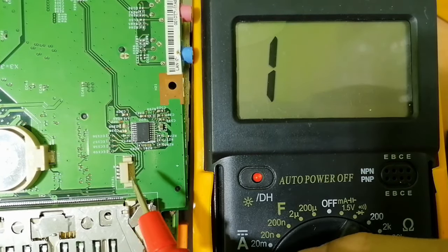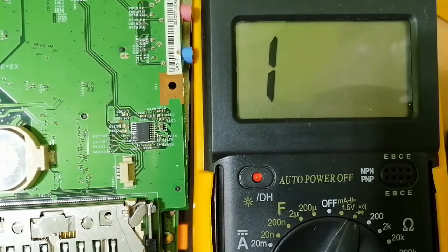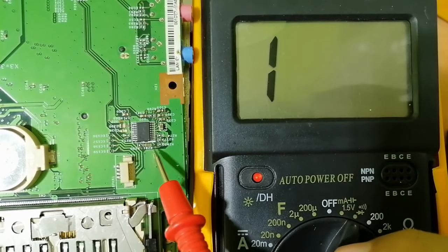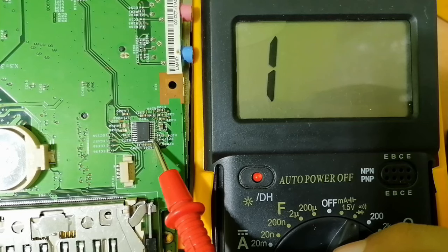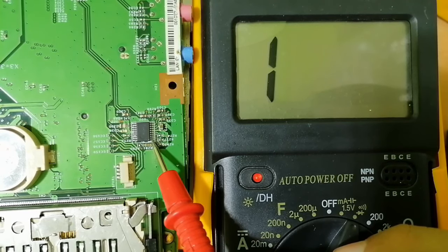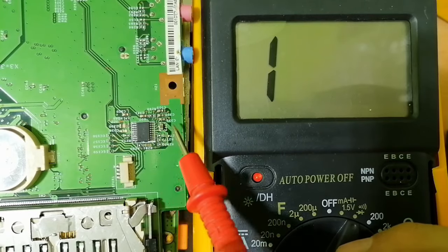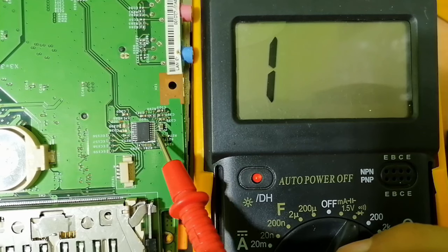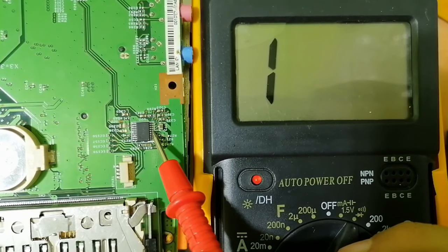So the third method is by checking the inputs and the outputs. Let's assume, for example, that this is the input of the IC, in this pin, and the output, for example, is 3.3 volt. To get 3.3 volt here, the IC first should receive the input signals, including the input voltage, the VCC, for example, 5 volt.